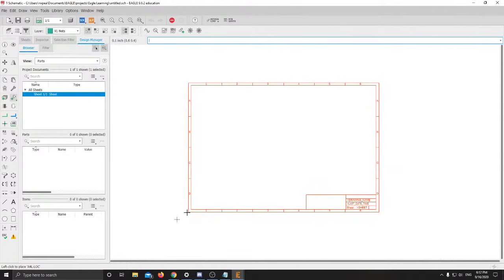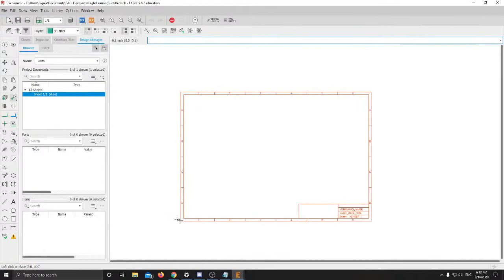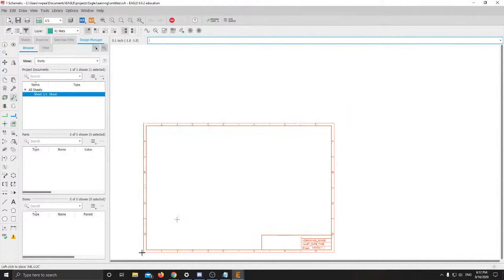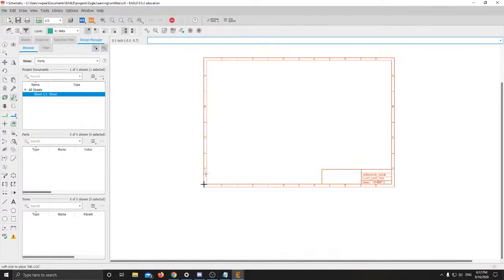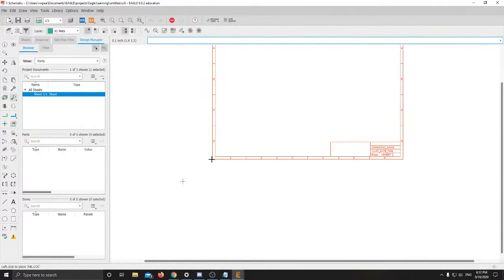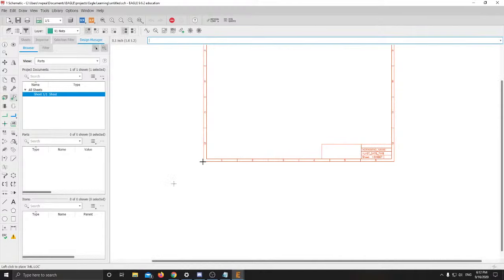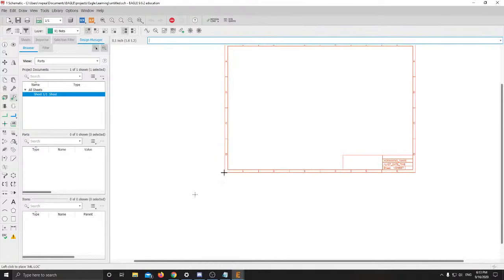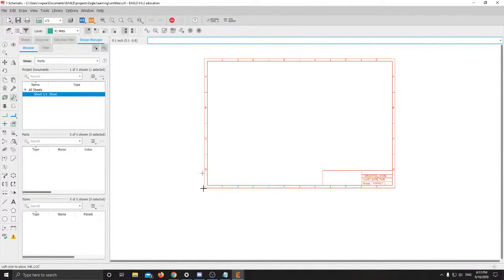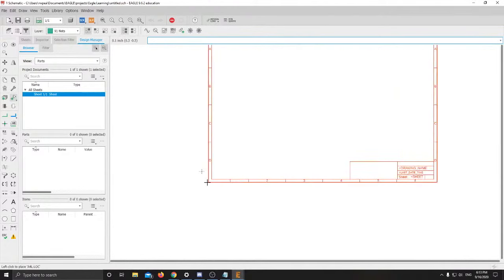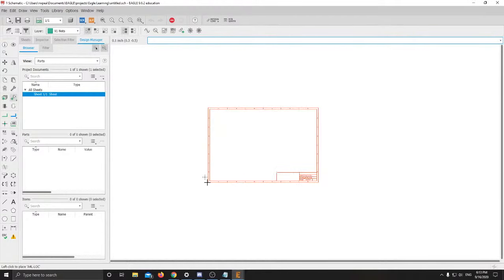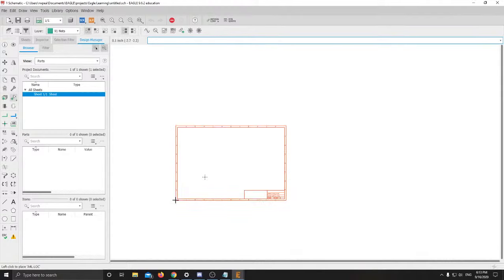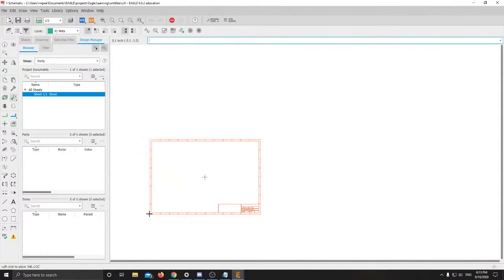You'll notice that I have to move it by the bottom right. That's where my cursor is. Then I'm just going to center it so that the middle's roughly at the origin. A couple quick controls in Eagle: to pan, you hold down the center click button, your scroll wheel, and to zoom in and out, you just scroll. I think you can invert it, but for me, scrolling towards me zooms out. So I'm going to go ahead and place this here.